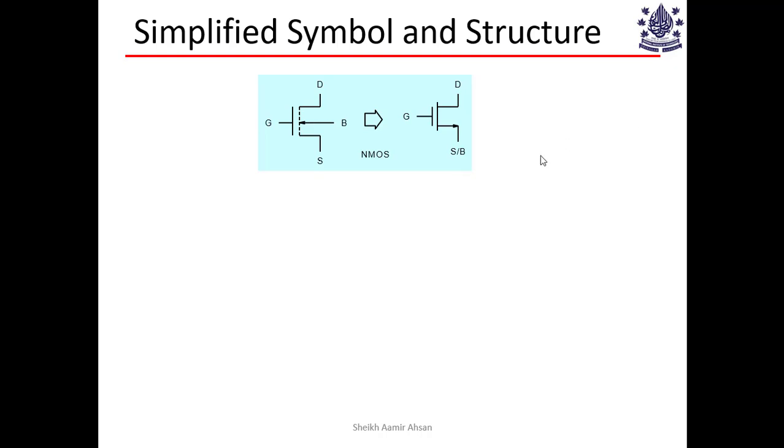When electrons are supplied, they have to go from source to the drain, right? So if an electron is going from the source to the drain, the current is flowing from the drain to the source. Okay, and if the current is going from the drain to the source, what is the direction of the current? Like this. It goes from the channel to the source, the current. That's why this arrow is drawn in this direction. In PMOSFETs, you'll see it happening the other way.